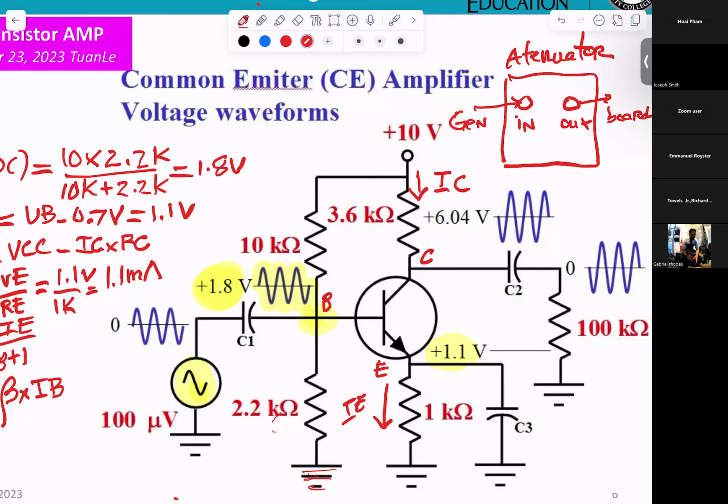They already prepare for you guys. When you need microvolt, 100 millivolt, 50 millivolt, they know the oscilloscope cannot do it, the generator cannot do it. So that's why they're adding the attenuator. They try to divide the signal, okay? So you can get to the voltage you want.